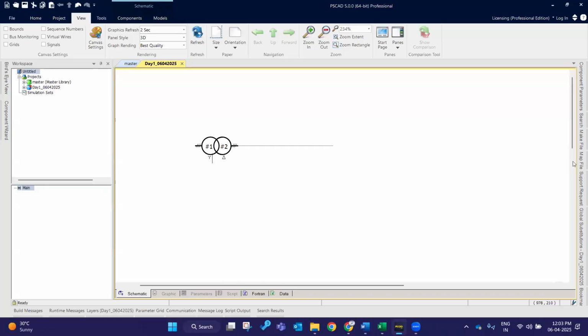Yes. So hope the screen is visible, right? At that time, during lightning, giving the lesser time step will only permit you to view the lightning as well as the lightning behavior. Why? Because all those things are high frequency transients. Even in switching action also. Suddenly, if you are energizing the transformer,